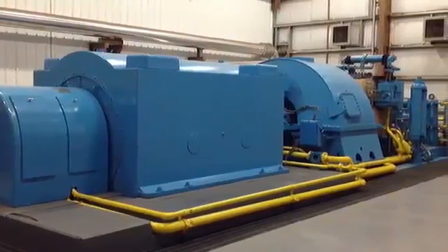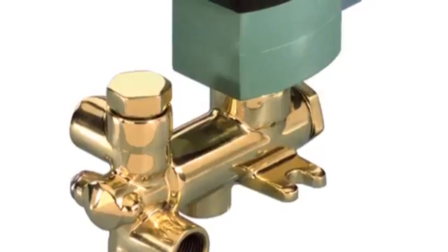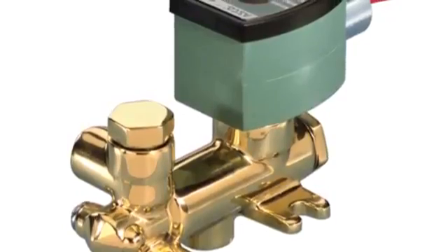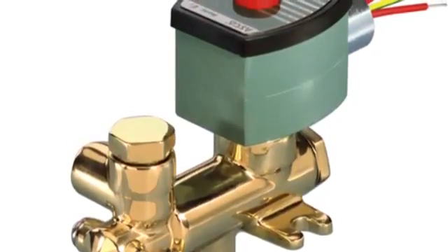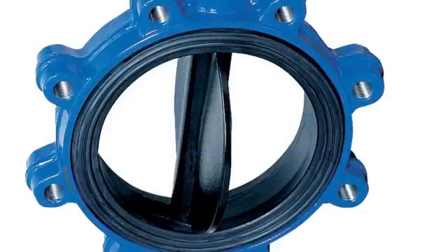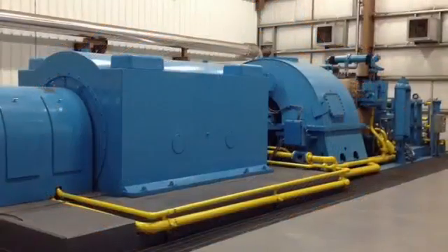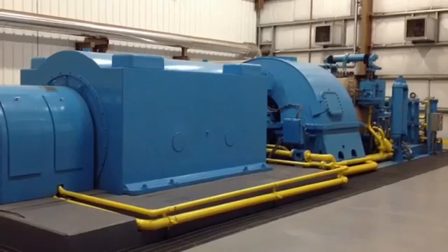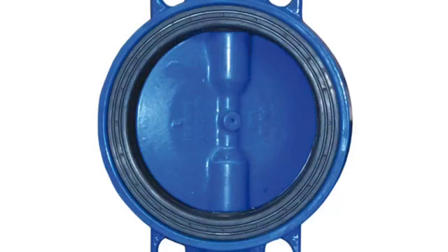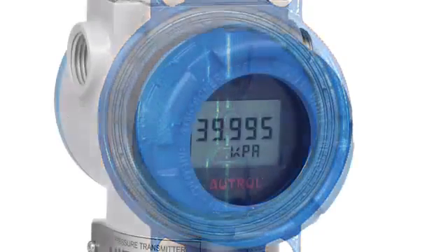Here is what actually happens. A pilot valve is connected to the plant air supply. The pilot valve is actuated by energizing a 120 volt AC solenoid coil. When the coil is energized, the valve is held open, allowing plant air to enter the pneumatic actuator for the steam valve. Air pressure is used to hold the steam valve open, allowing steam to enter and cause the turbine generator to rotate. If the signal from the safety PLC opens to de-energize the pilot valve coil, the pilot valve will close, cutting off the air supply to the steam valve, which will cause the steam valve to close. This is an example of a de-energize to trip, or DTT, safety function.